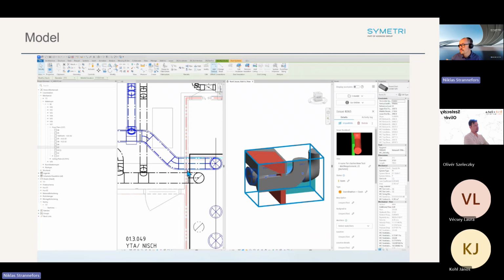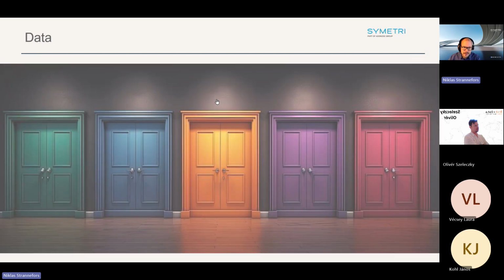Because if they say, we're done, can you check it? You guys can then just create a door schedule, include elements from linked files, and you will see all the parameters yourself. And we can start sorting and checking those. So we could see, okay, we have a min clear width of 1.2 meters. What kind of size are all the doors with 1.2 meters? We can go through it. I think I have it in this one. Yeah, I have it in this one.